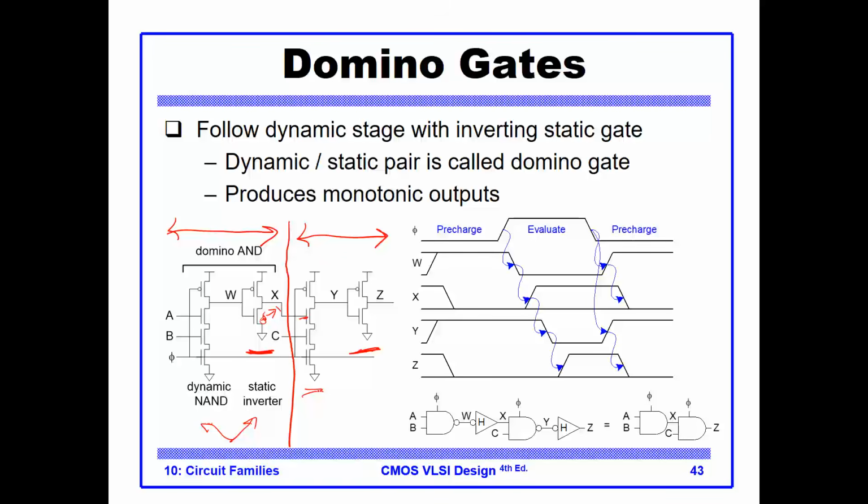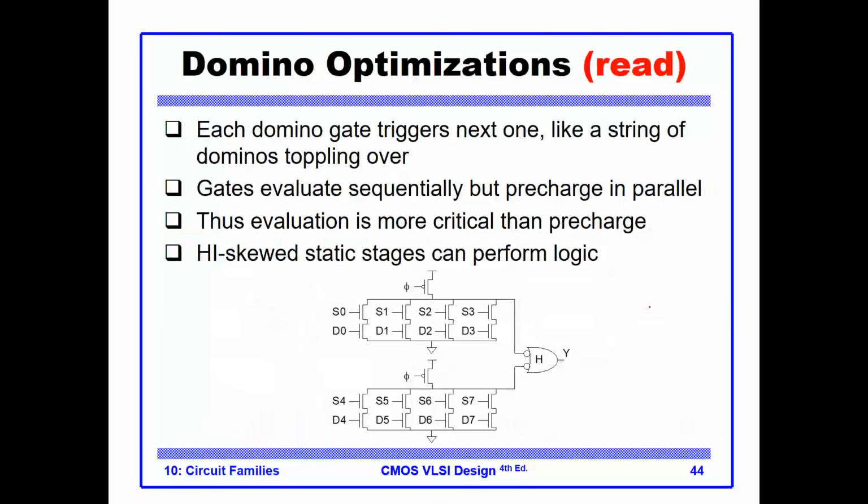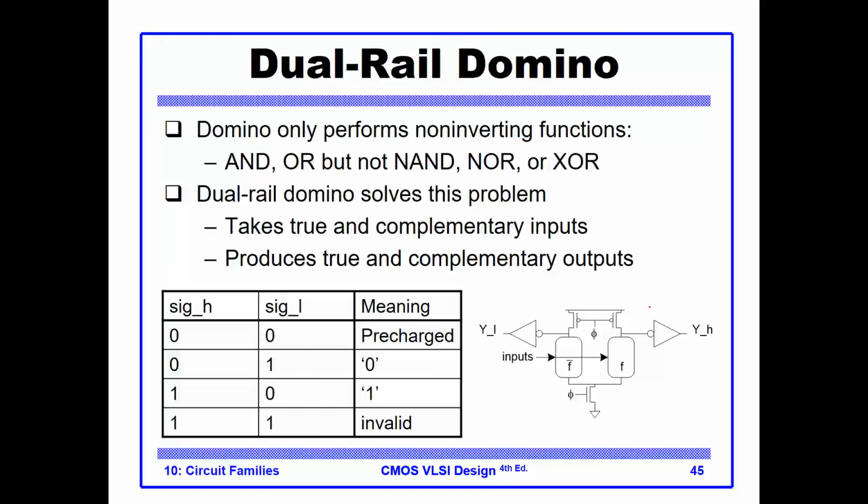They force certain transitioning of the signal. Either they are static, they don't change, but if they change, the inputs to the dynamic circuit change from 0 to 1, which is the legal case. You can read about the design of a multiplexer using domino, but I'm going to be selective here in what I explain. So that was reading material.